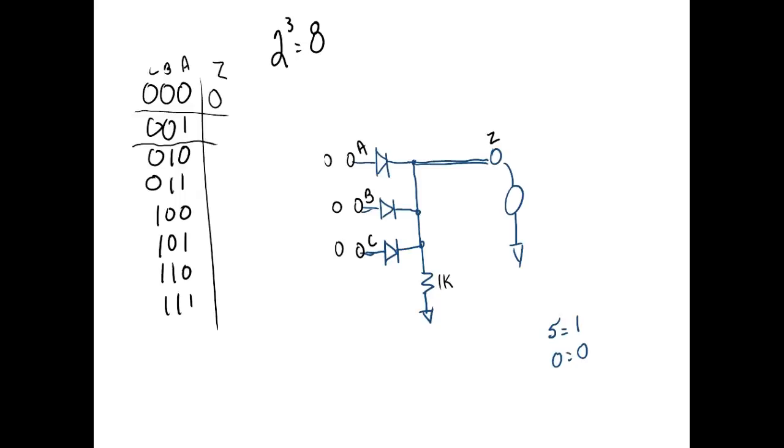How much voltage does a resistor draw? V is not equal to V. What's V equal to? Ohm's law? Okay, so if you have no current flow through a resistor, it drops no voltage. If it drops no voltage, that's effectively bringing this and putting it right there, right? You understand that? It's dropping no voltage, so it's acting like a piece of wire.